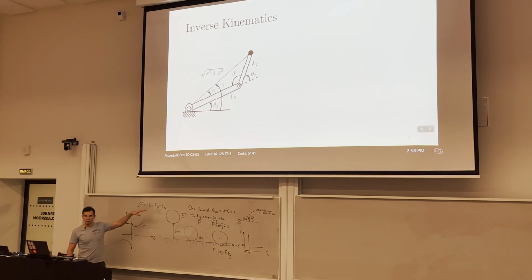It's still possible, but if you change, for example, a mass or a length of a link, the coefficients must be different, right? Because those coefficients are only for this system. For example, if your robot takes an object, the mass of the system is different, and it will not follow the trajectory.